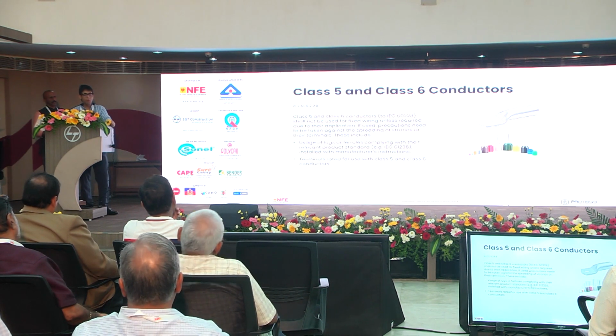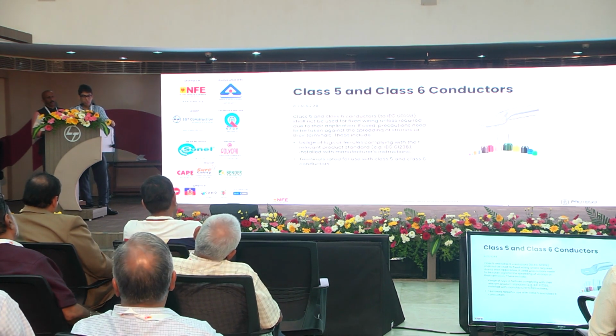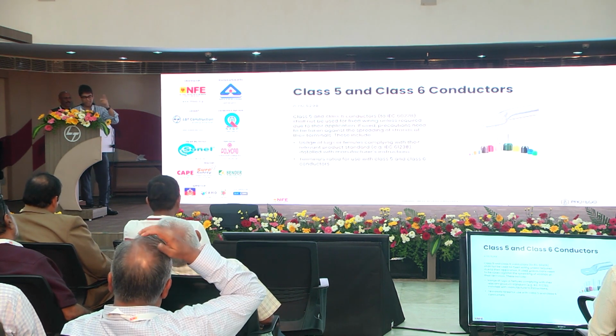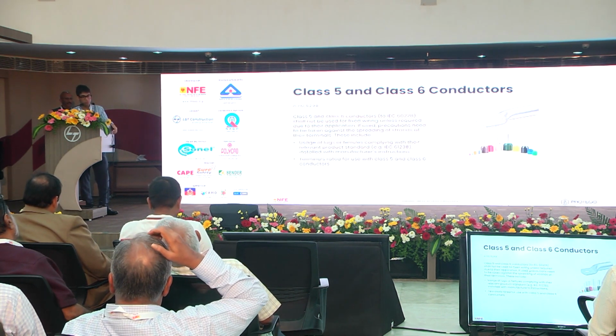Yeah, that's a very good point because when I was looking at shaped conductors, most armored cables are going to have shaped conductors, you cannot just use a traditional lug. Like he said, there's not going to be 100% surface to surface area conduction. So I know Dowell's has a product, and that's a good product for this. Thank you.